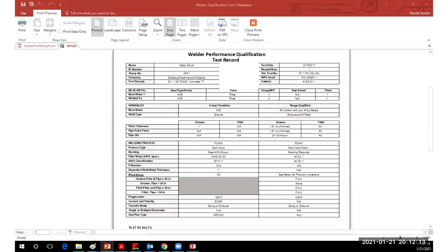I did special inspection up here in Northeast Tennessee for a year and a half or something like that, and it was a big eye opener. I actually went to at least two contractors where, when I looked to review their welder performance qualification records, they told me, here, this is the one for our certified welder. I said, well, he's not the guy up there welding. No, but he's on site whenever he's welding. So they were under the impression that if a certified welder was there, they were good to go.